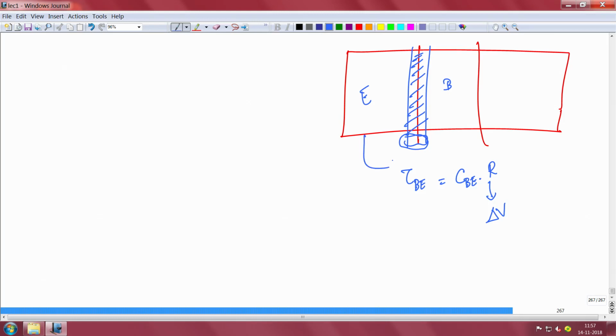So if you connect this in a positive, forward bias, the resistance is the change in the base emitter voltage with respect to the current that is going out, which is IE, but IE is almost equal to IC, so I can say this is IC, right. The inverse of this will be called the transconductance: the output current with respect to the input voltage, how much is it changing, right.